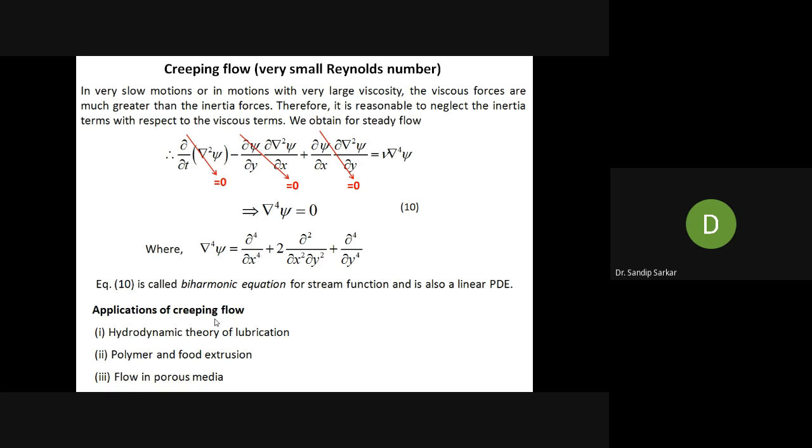Suppose how the water is getting sucked by the stems of a big tree, how the fluid is flowing through the suction caused by a big tree through their stem, which is basically capillary motion. In those kinds of motion, the velocity of the fluid is very small. Those kinds of fluid flow are called the creeping flow situation.